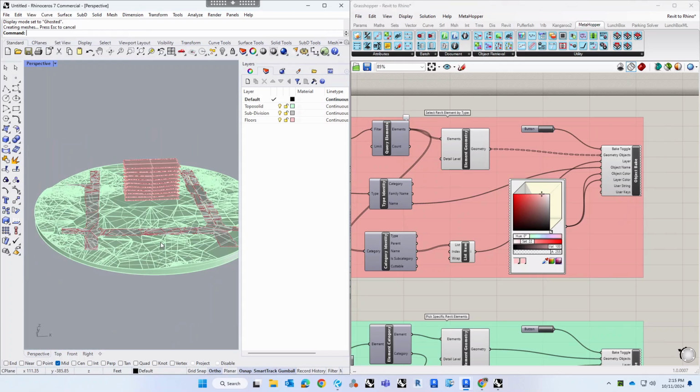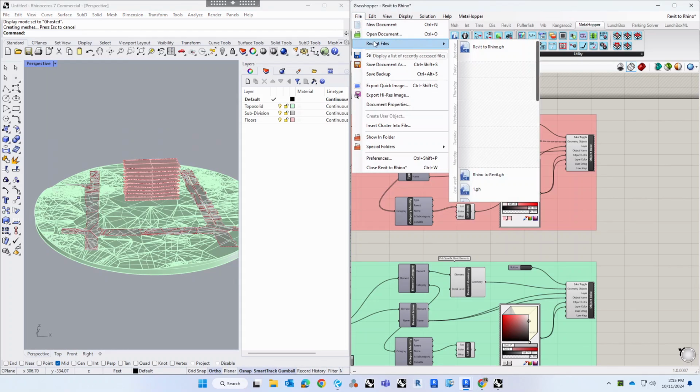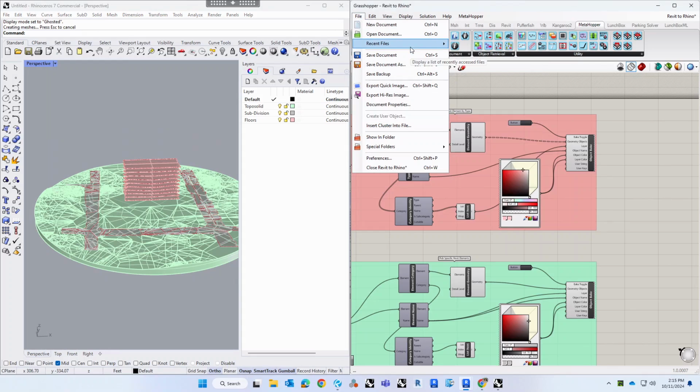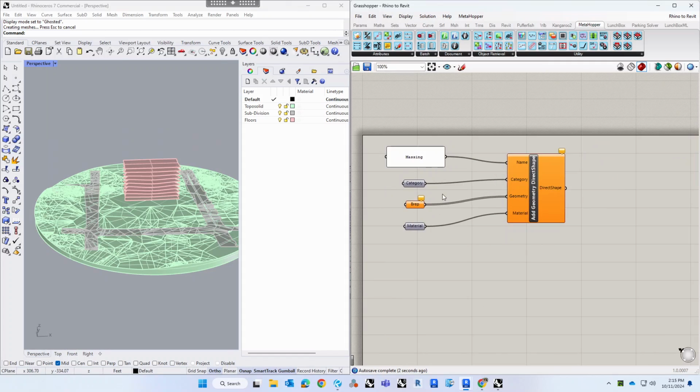So now I can do whatever I need to within Rhino, create some crazy nurbs curves, whatever. And then, of course, you can go back from Rhino into Revit. That workflow is a lot simpler. Back to Revit. So again, you don't really get any of the functionality that you get by importing directly into the conceptual mass environment. But if you are just bringing in elements, this is a pretty easy way to do so. All I have to do is right click, set one Brep, and select whichever component you want to bring in.